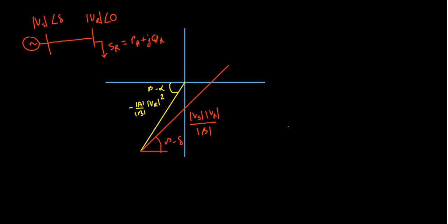And these are the A, B, C, D parameters of the line. Now once the line is there, its ABCD parameters are fixed. That means the magnitudes of ABCD as well as their angles. So magnitude of A and its angle alpha, magnitude of B and its angle beta, you cannot change once the line is ready. So we have got the summation of these two phasors, minus A upon B VR square,